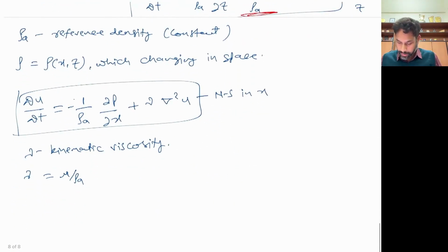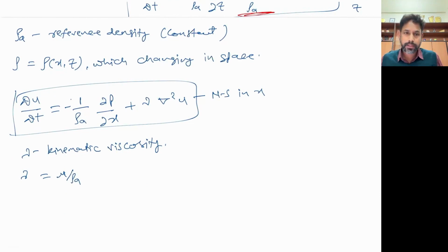And this assumption is called the Boussinesq approximation or Boussinesq assumption, and this particularly is applicable when the density difference is not very large. If the density difference is very large, then yes, we do have to consider the effect of density variation in the field to be able to model the flow more accurately. But if it is less than 10%, then by neglecting the effects of density variation, we can still model the flow quite accurately, or approximately to its true behavior. Okay, thank you.